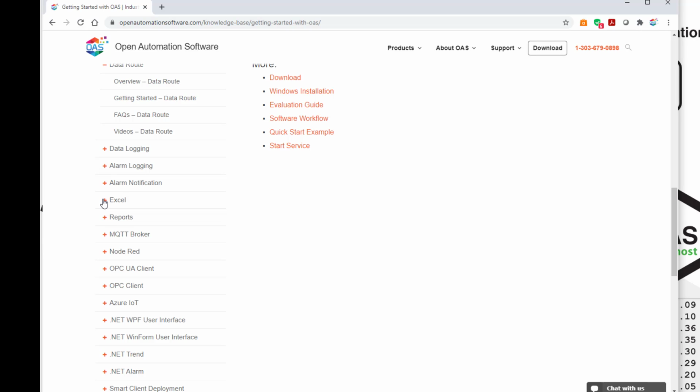You can send data to AWS and, of course, to MQTT brokers. OES also has its built-in MQTT broker that's extremely high speed, the highest speed open broker that you will find available. All you have to do is define the data source in OES, and then you'll be able to pick that data up from that third-party MQTT client as you like.